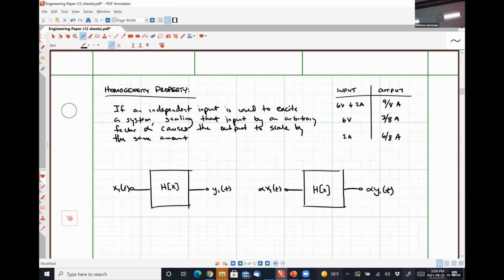Absolutely, yeah. So the coefficient won't change, but the amount of voltage or current being supplied by that dependent source likely will because of the configuration of the circuit. Yeah. So you won't have like 5ix suddenly becomes 3ix or anything like that, but the value of ix itself probably changes from the varying configuration.